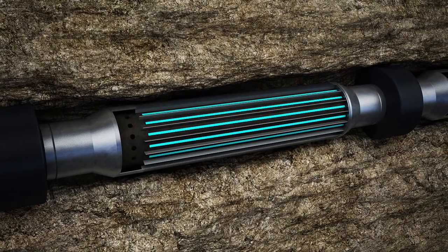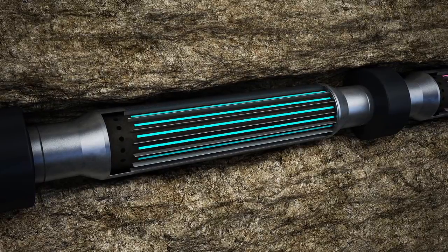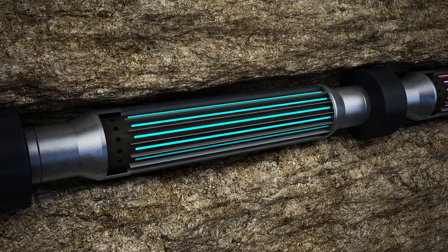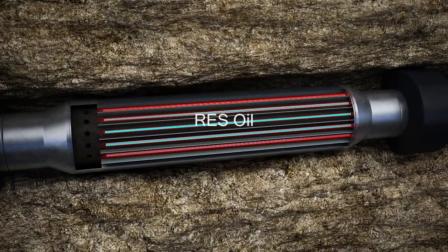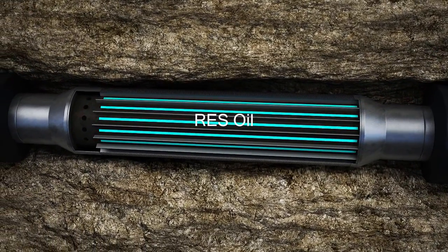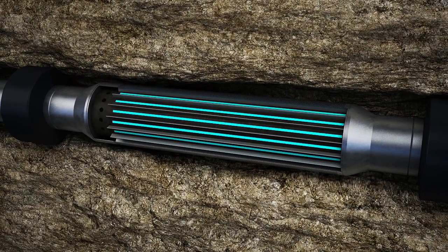These types of sand screens have a nozzle at one end of the joint that regulates the flow from the reservoir into the main flow stream. The RESMAN rods are produced at the RESMAN facility and then integrated into the screens during the screen manufacturing process. The different colored rods shown in each screen represent the unique chemical compound contained in the rods. In this example, 7 unique chemical tracers are used to measure oil inflow distribution.